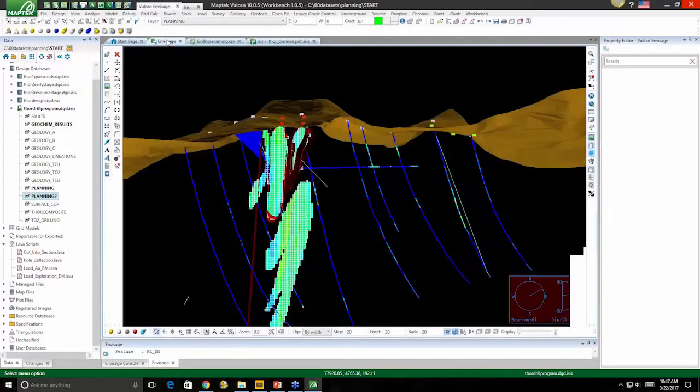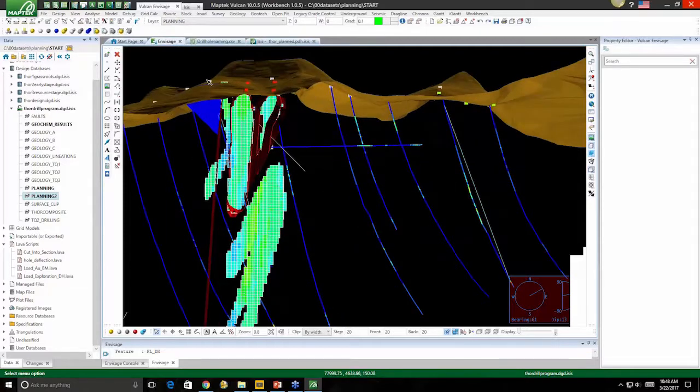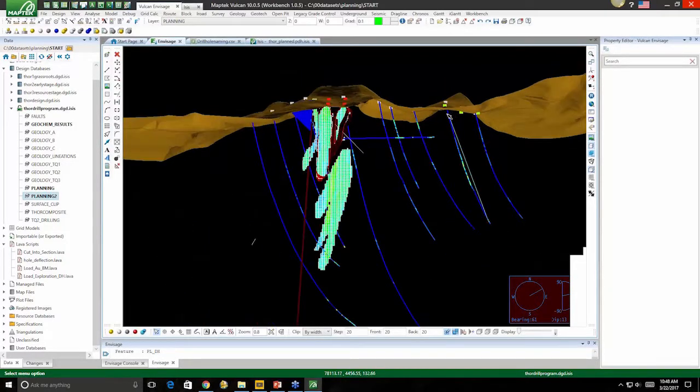So we'll leave that there for a second. The next thing I want to talk about is now that I have these existing holes, how can I move them? So maybe for this one I wasn't quite on that surface there, or this one I might want to move a little bit. I know I need to validate this hole, but I might want to drag that a little bit over to the right to match it up where that hole is.